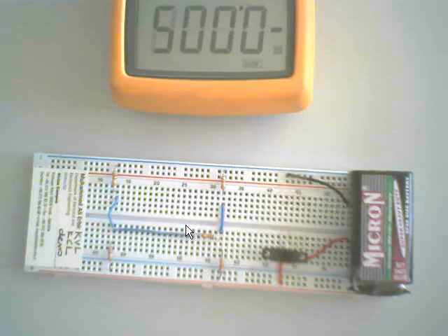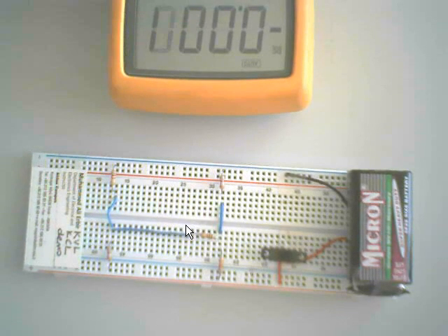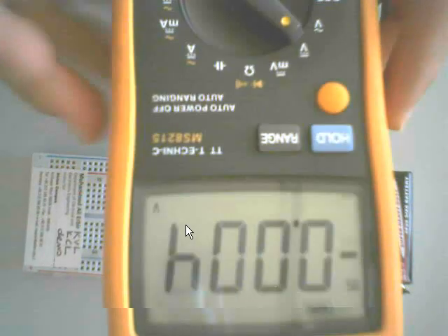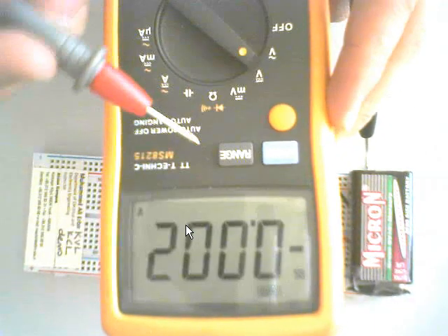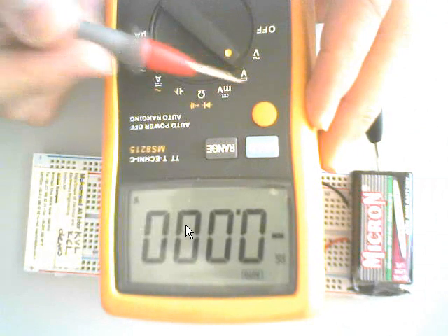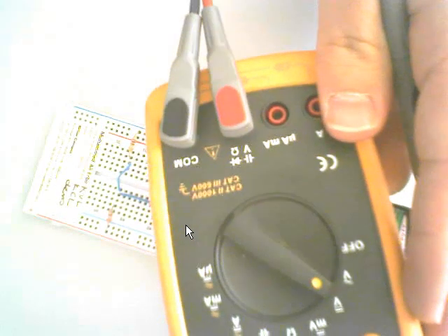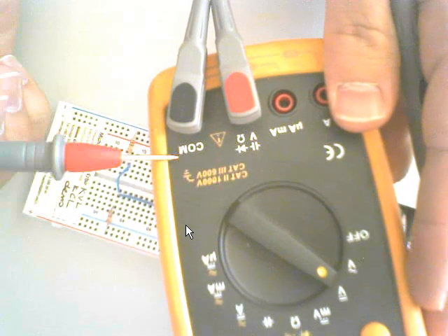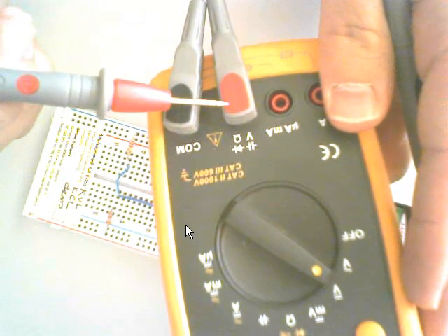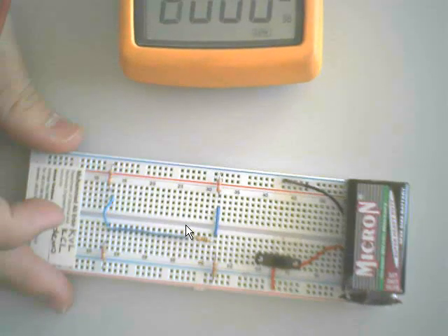This is the multimeter. I have adjusted it for DC voltage. Here it's in DC voltage measurement mode, and the probes are connected like this. Black is connected to the common, and the red one is connected to the voltage mode. Now